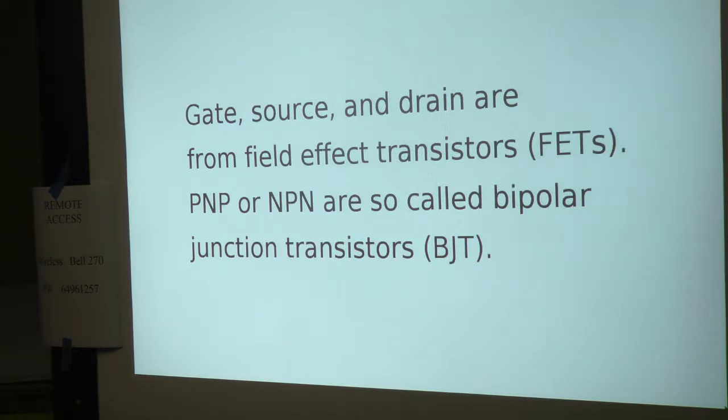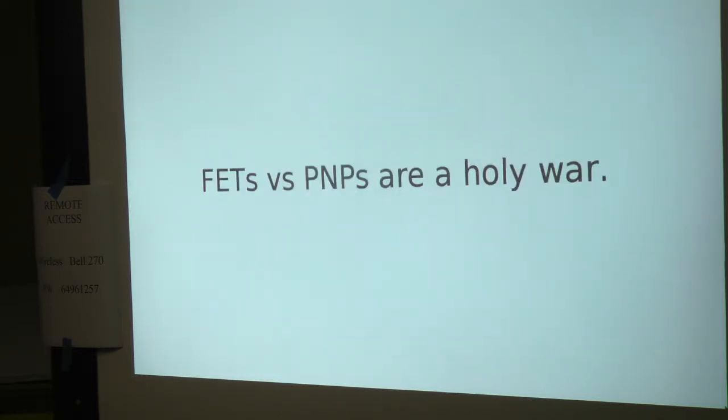It's just the type of charge that moves in that particular type. If I could just quickly add something there: when I'm working on an old radio, if it's a positive ground, it's nearly all PNP. If it's a negative ground, it's nearly all NPN. Exactly. Yep.